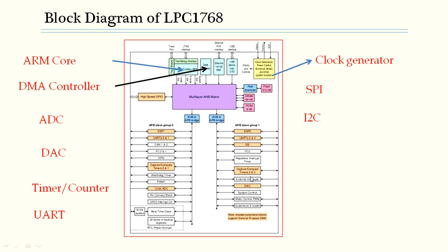Yeah, SPI, then you can see these are the small blocks. I2C you have, right? Fine, you can see the blocks, the details can be obtained upon. It's a bidirectional bus for inter-IC control, which uses only 2 wires, right? It's the serial clock line and the serial data line.